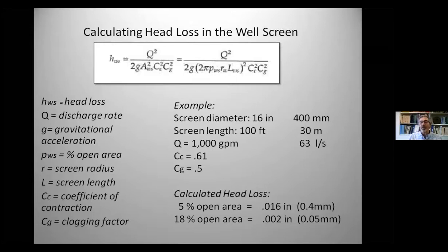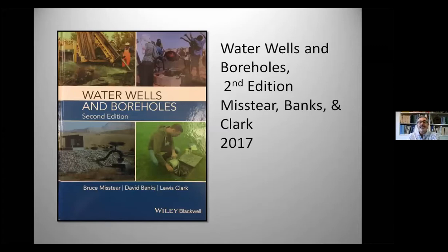So overall, very, very small contribution to the overall head loss, the overall drawdown on the well, just from the screen itself. So this tells us as long as we develop that screen properly, more open area is not necessarily going to give us higher efficiencies or any more or any less head loss. This is another new book that comes out and answers the same issues.